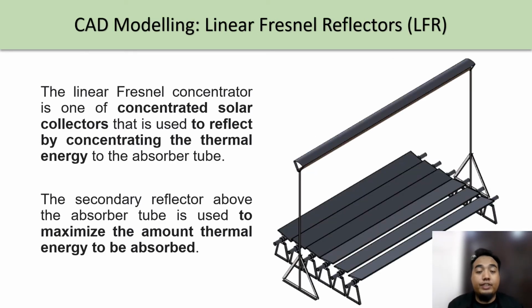Just now I have shared about the LFR, this concentrator, and the PEM. So I will go into detail. Before that, this is the CAD modeling that I will refer to during my CAD design stage. Basically, the linear Fresnel concentrator, or we can say reflectors, is one of the concentrated solar reflectors that is used to reflect by concentrating the thermal energy onto the absorber tube. We have secondary reflectors above the absorber tube to maximize the amount of thermal energy to be absorbed.